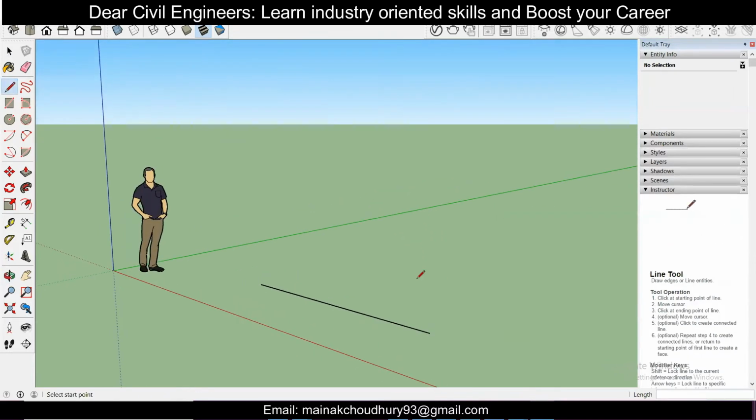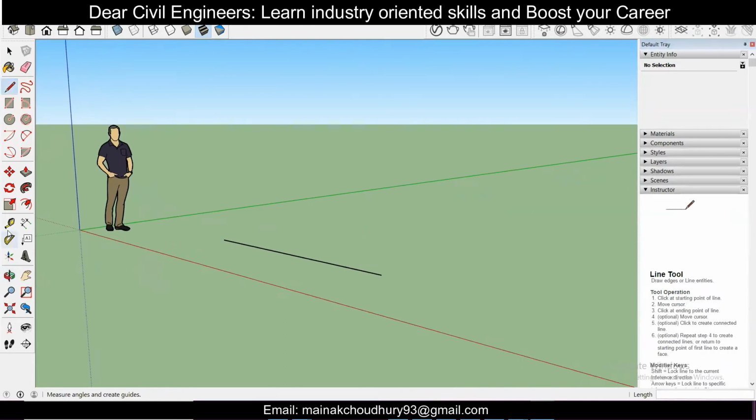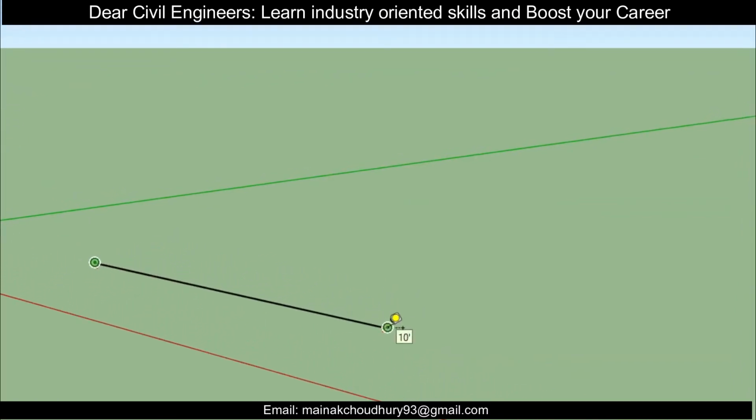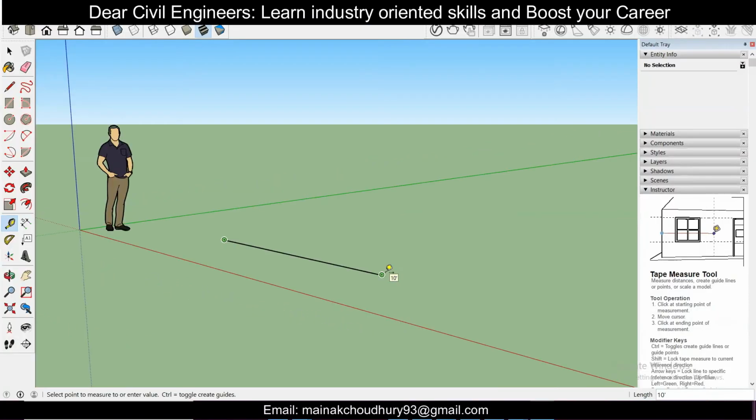After that, we'll press shift plus mouse middle button, that is the pan, and then use this option, that is the tape measure tool. You can see, I'll click on here, and I'll click and just move it up to here. You can see the 10 feet option showing in the screen. There's a 10 feet, that is 10 into 12, that is 120 inches. So automatically this will happen.